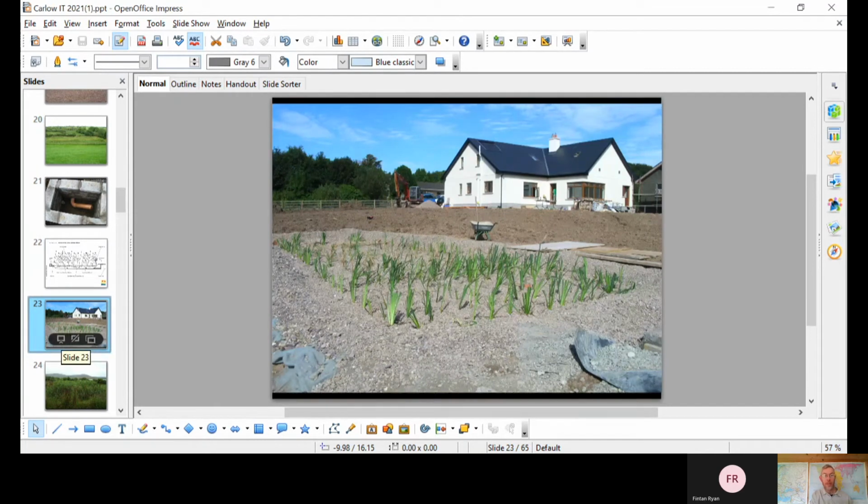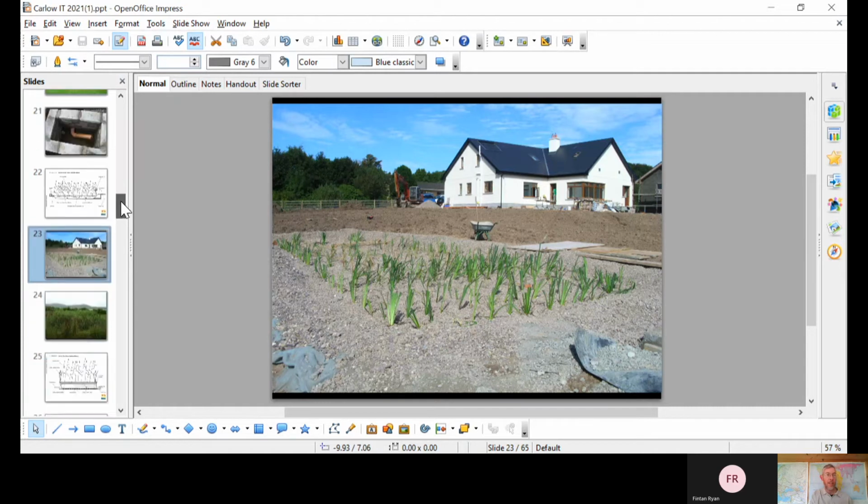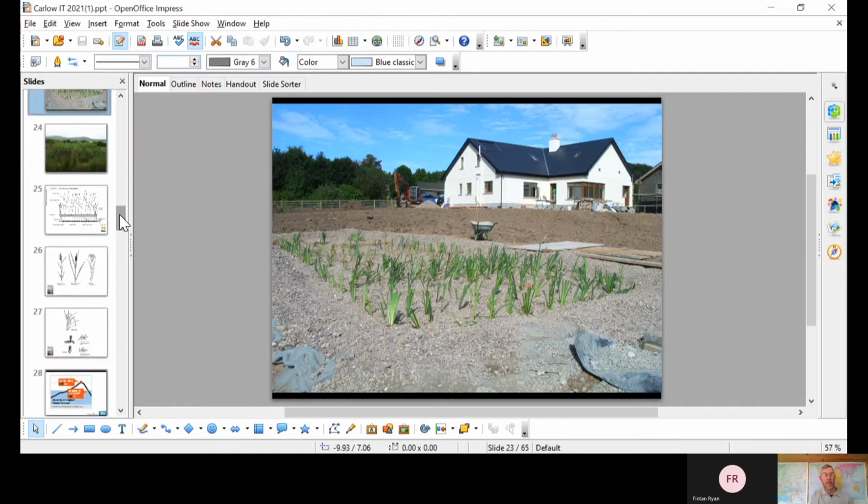Here's a gravel reed bed system in North Cork, and you can see just the planting within the gravel, and the water surface is literally just below the surface of the gravel. Something to watch if you're designing or building these is to make sure that the gravel is level. On this side, when we arrived, the gravel was about 4 inches higher at the top left than it was on the bottom right. The risks there are that these plants will dry out, and in the lower area the water will break the surface and become a potential pathogen risk within the garden. So getting the levels right is important before the day of planting. What we did there is we just got a couple of shovels and rakes and leveled it out before we started the planting itself.